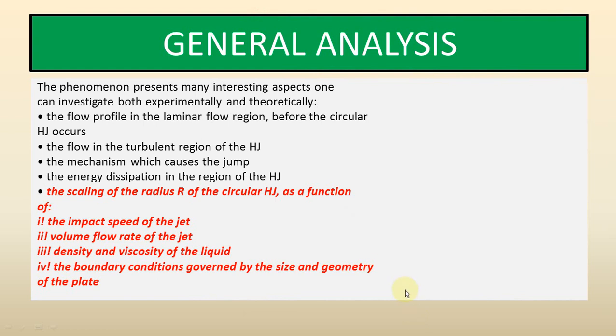So here we will see the general analysis of the hydraulic jump. The hydraulic jump is a very interesting phenomenon, and you can investigate it both experimentally and theoretically. We will discuss only the last part, that is the radius r of the circular hydraulic jump as a function of the impact speed, volume flow rate, density and viscosity of the fluid, and the boundary conditions governed by the size and the geometry of the plate. We will discuss that in today's video. All the turbulent flow, eddy formation and energy loss we will not study here. We will just study the general analysis.